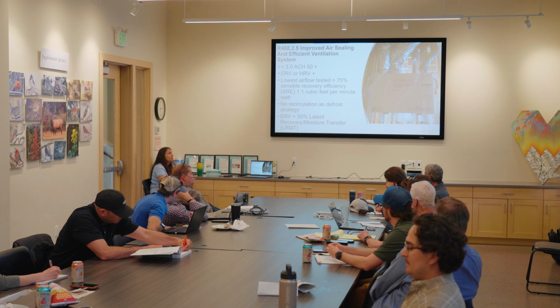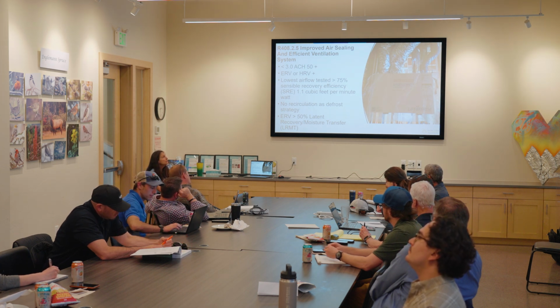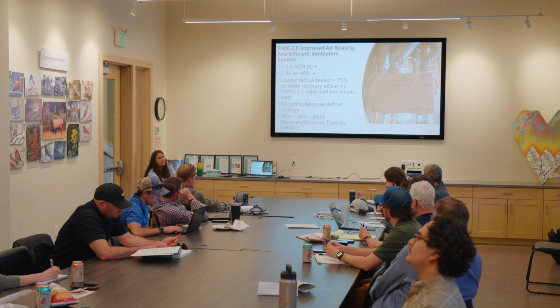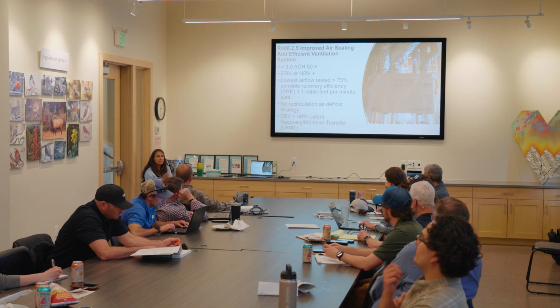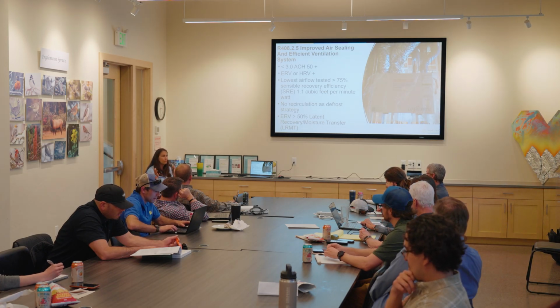Because of the sensible recovery efficiency, I think it's 65%. It might be 68%. 68 at 32 degrees, if we're just installing an ERV or HRV, it has to do that.